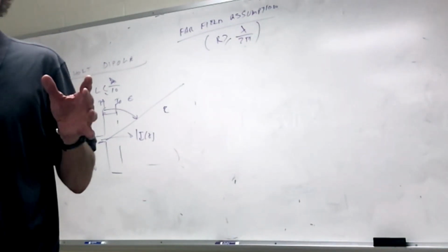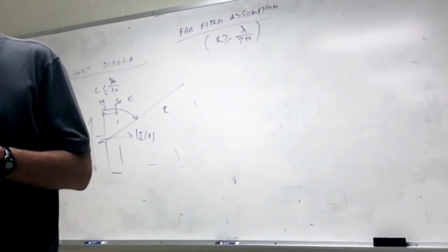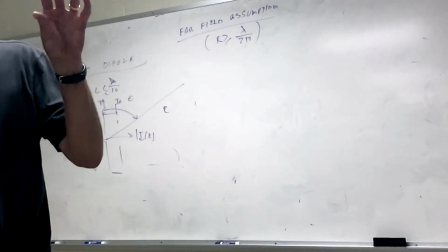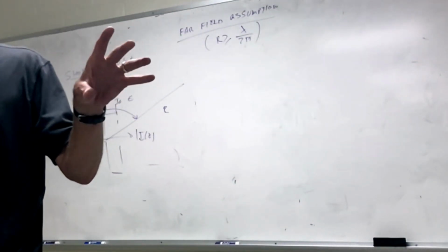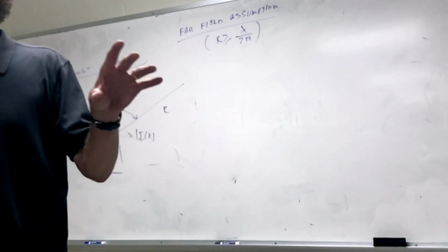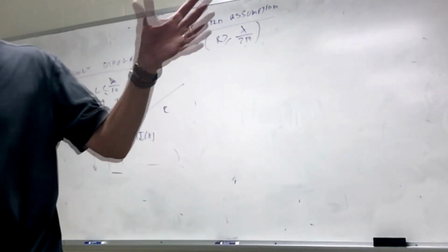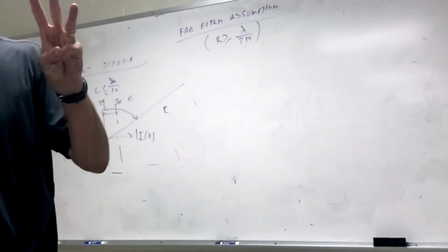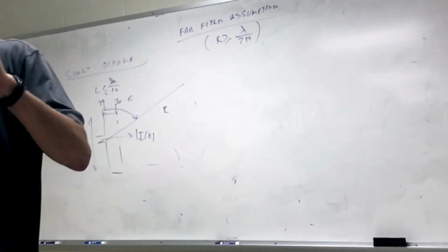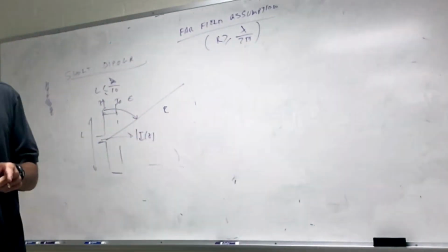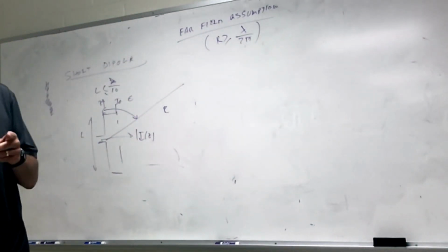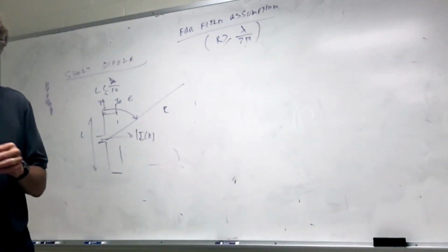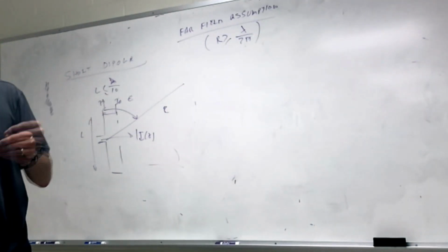But in the near field, stuff gets a little more complicated, and Wentworth kind of hand waves at this. He lets you take the magnetic vector potential, take the curl of it to get the H field, and you're going to get several terms for the H field, and 3 for the electric field. The only one you care about is the 1 over R variation. That's a propagating wave. The other field terms for both H and E that are functions of 1 over R squared and 1 over R cubed are related to near field energies.